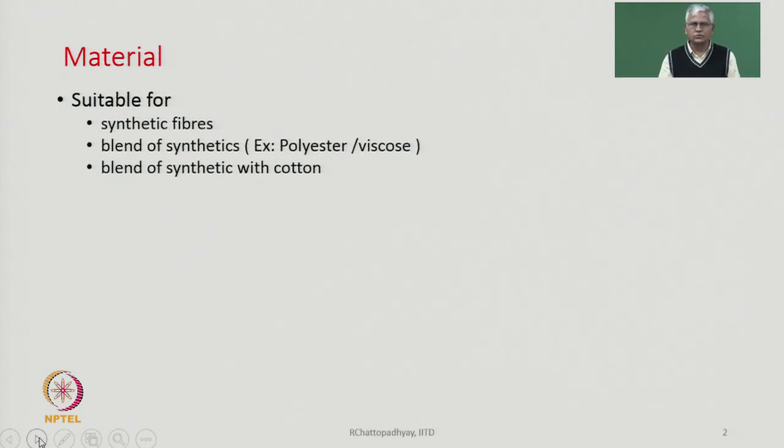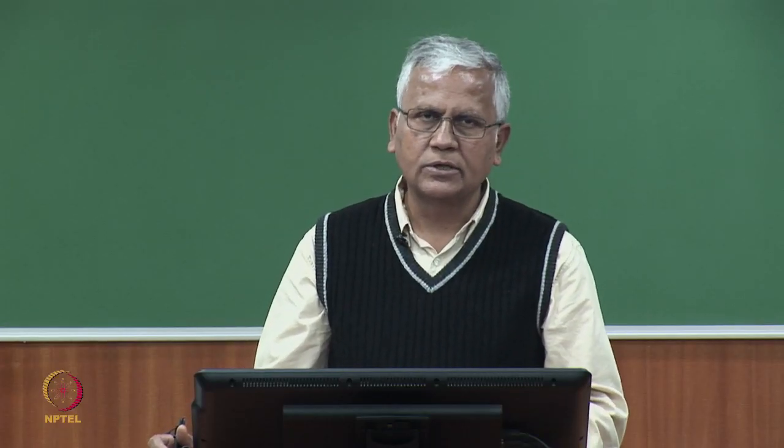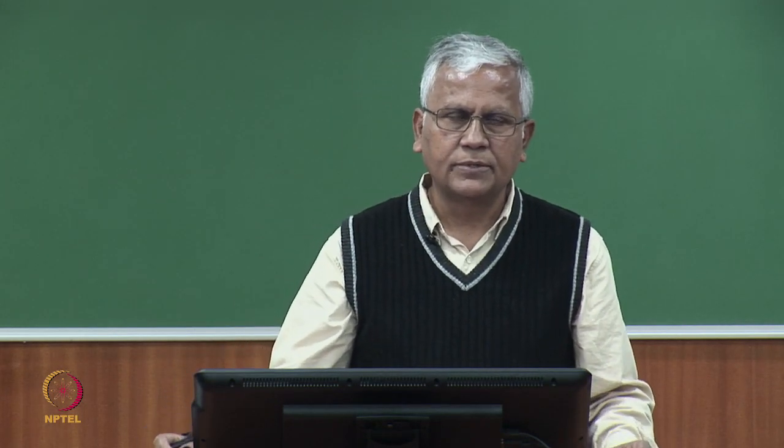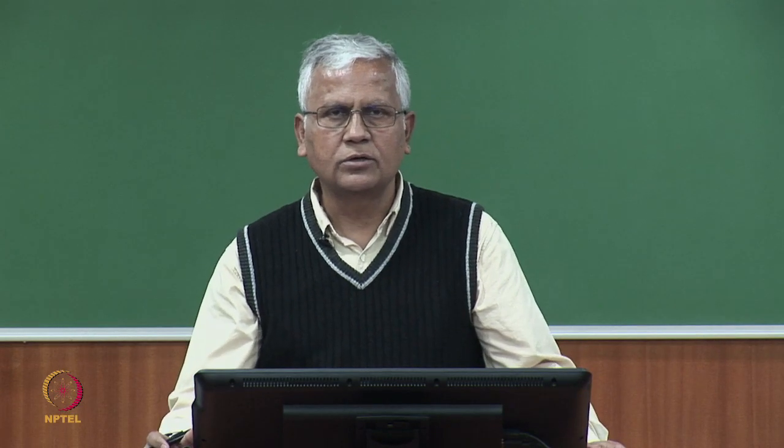So, cotton synthetic blend also can be easily processed, but for 100% cotton it is not really so suitable, though people have been trying to process 100% cotton fiber, because we all know that cotton contains lot of dust particles, and therefore, even though we try to remove the dust by processing fibers on blow room, on carding machines, and sucking out dust on draw frame also, we try to remove some dust and some trace particles by combing action also, but even then whatever dust is still left can also create problem with the nozzles of the air jet spinning, and therefore, 100% cotton is normally not processed.